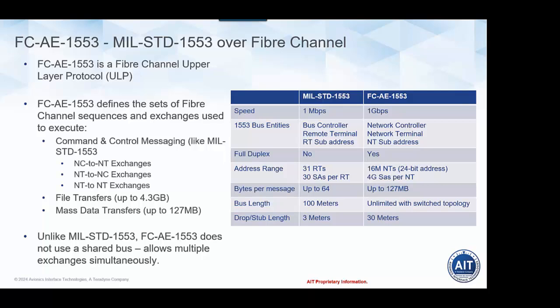The maximum size of messages that can be exchanged during the transfers is also much larger, so you can do up to 127 megabyte message transfers, where with 1553, 64 bytes is the maximum size of a message. And also because it uses a switch topology, you're not limited by the maximum length of the bus. So you can put switches along the way, and by utilizing switches have a kind of unlimited length of a bus, or run of how far you can separate the nodes on an FC-AE-1553 bus.